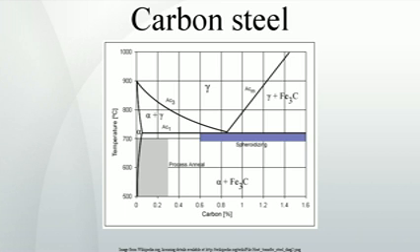Higher carbon steels. Carbon steels which can successfully undergo heat treatment have a carbon content in the range of 0.30 to 1.70% by weight. Trace impurities of various other elements can have a significant effect on the quality of the resulting steel. Trace amounts of sulfur in particular make the steel red short, that is, brittle and crumbly at working temperatures.